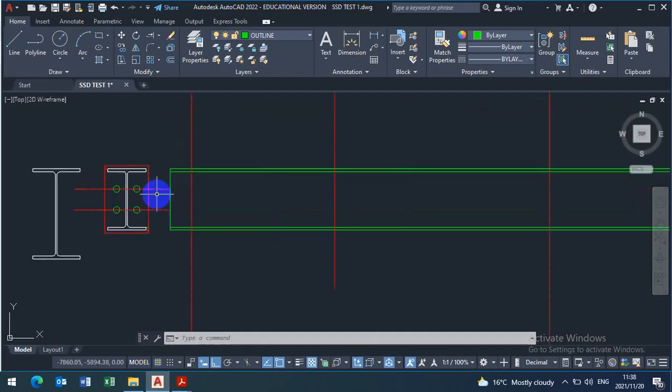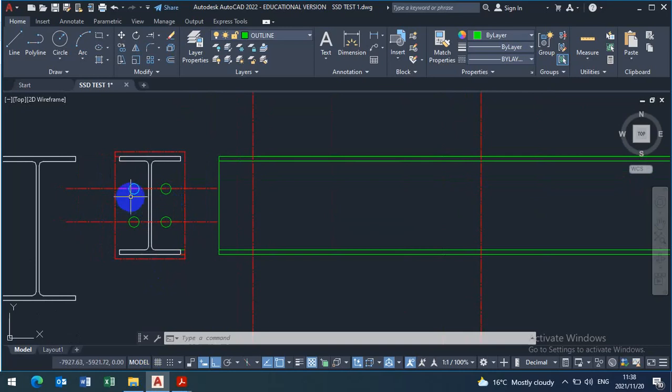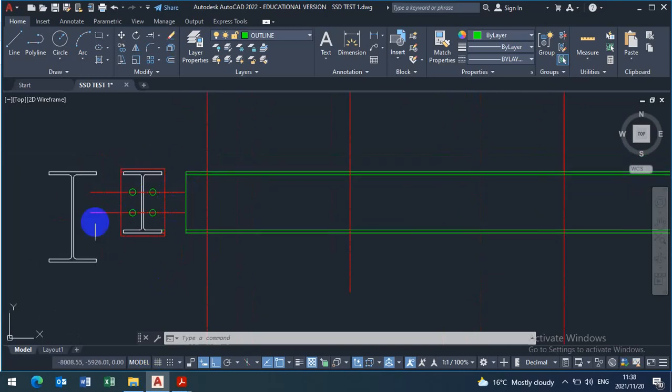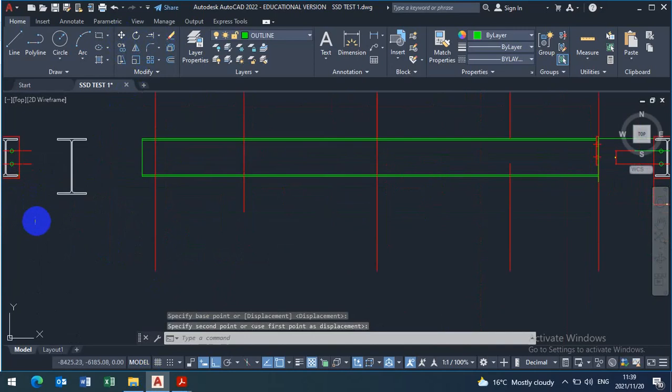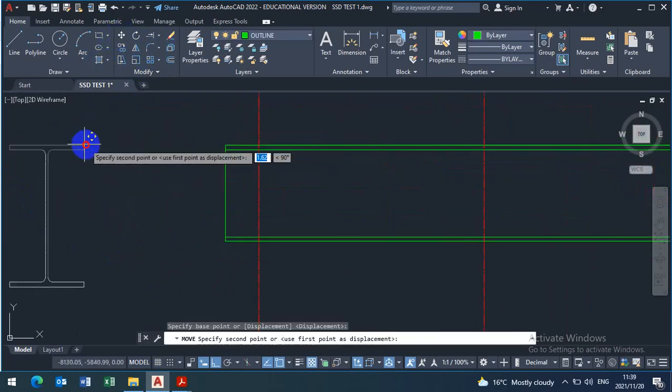Let's finish the notching part. With the notching part, you need to know that this beam here is coming in here, so you can now move this away. The end plate detail, you can move it somewhere this side, and then try to bring this beam near.